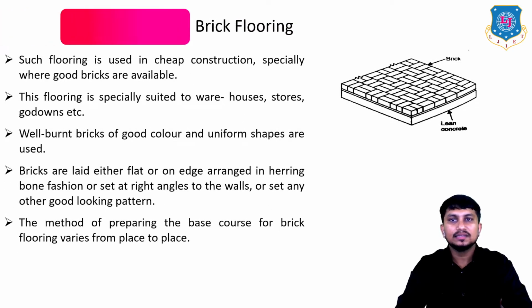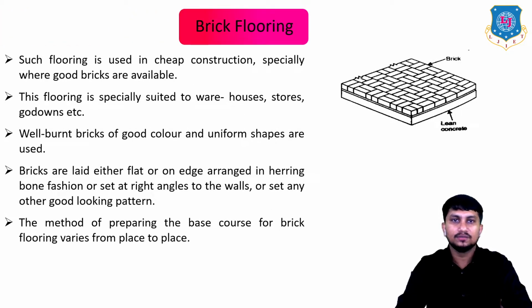Now let's see the brick flooring. Such flooring is used in cheap construction, especially where good bricks are available. The flooring is specially suited to warehouses, stores, godowns, etc. Well burnt bricks of good color and uniform shapes are mainly used in this type of flooring. Bricks are laid either flat or on edge, arranged in herringbone fashion, or set at right angles to the walls, or set at any other good looking patterns.